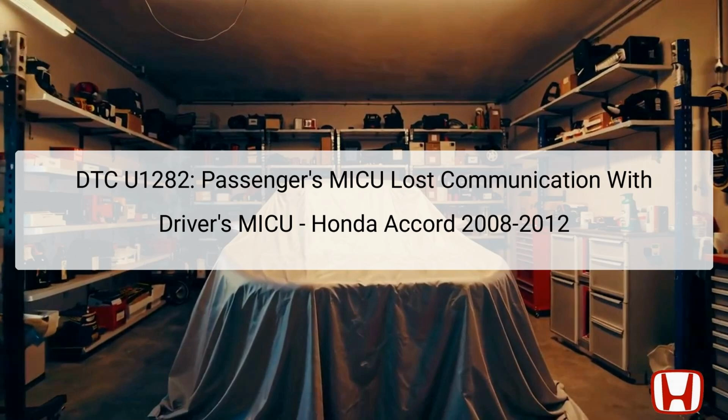The passenger's MICU is typically located under the dashboard on the passenger side, while the driver's MICU is placed similarly on the driver's side. When communication between these two units is interrupted, it can lead to various operational issues and can set off the DTC U1282. The importance of resolving this error is highlighted by the role of these units in maintaining the functionality of multiple systems, ensuring that the vehicle operates smoothly.